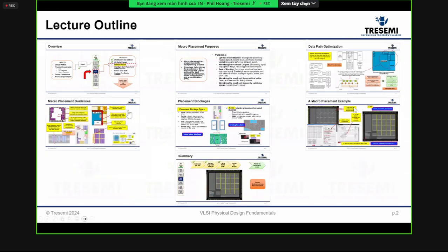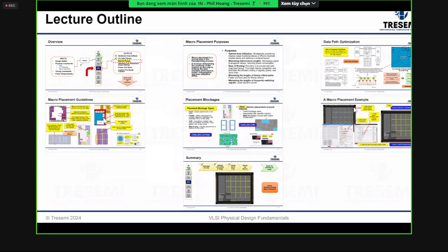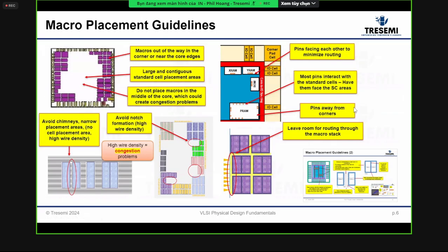And then the next few things involve various things. It's just by experience, you know that when you place all these memories, the best location is on the boundaries, on the periphery, leaving a very good contiguous area, meaning that everything is connected together physically without interruption in between.